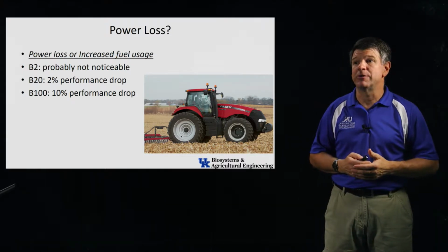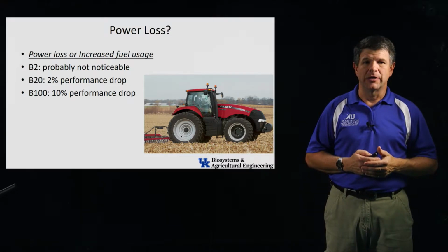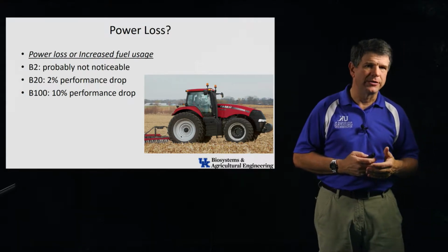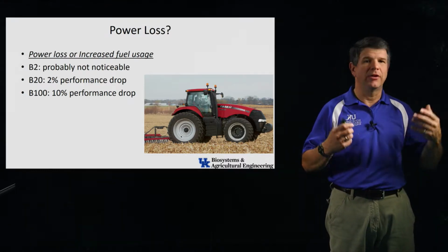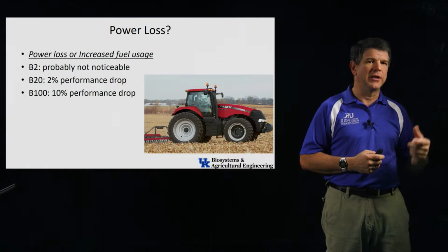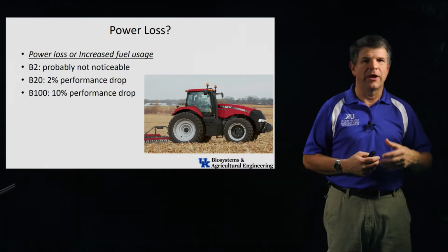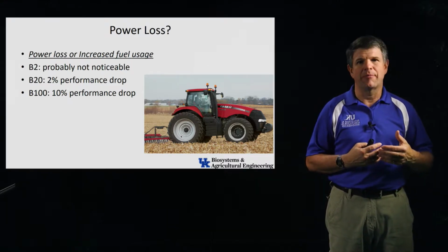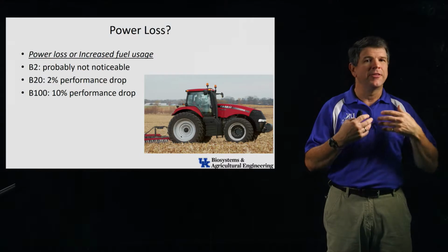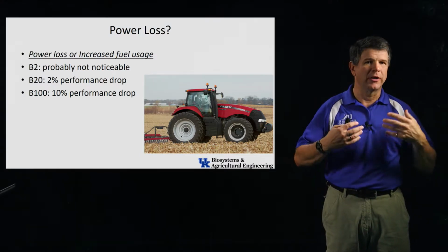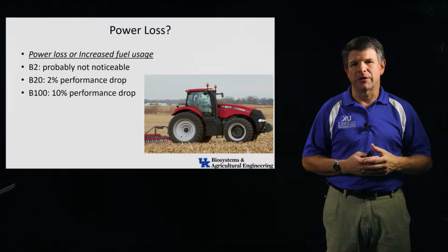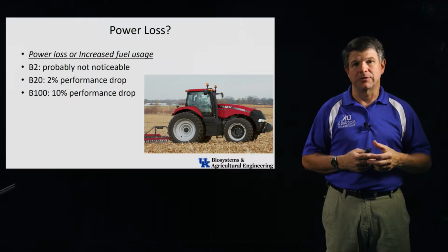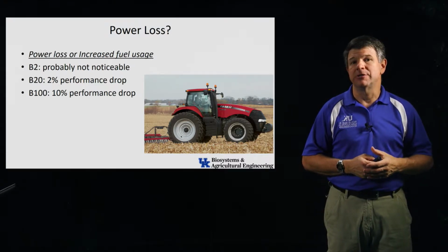So that's the kind of performance that we'll see with the different fuels going into the engine, as long as the engine can burn it. And different engines, again, will compensate in different ways. Some of the modern engines have a lot of sensors in the fuel and in the airstream, so they know how much oxygen is in the airstream and how much oxygen is in the fuel. And so they can actually change a lot of the operating parameters of that engine. They can change the timing of the injection or the spark. They can change how the valves open and close and so forth, and all that will change how that engine can utilize the different fuels. And so some of the modern engines really compensate very nicely for them.